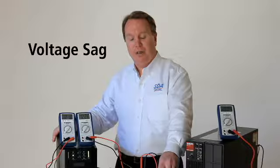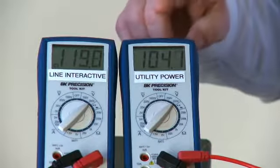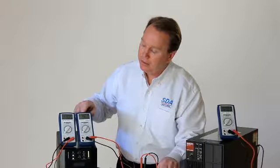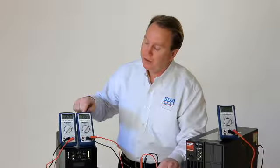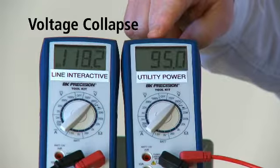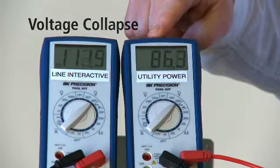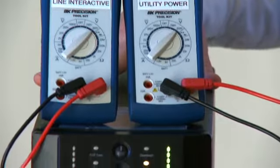Let's continue on and let's demonstrate a sag. Now our utility continues on close to the 100 volts, down into the 90s, and again our AVR is kicking in. We're going to drift, and then the utility decides to collapse. So we get down to a very common voltage level, about 84, 85 volts. Now we're into a full battery event.